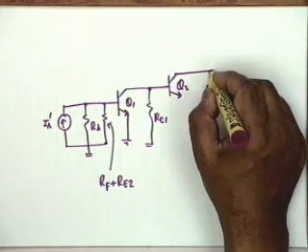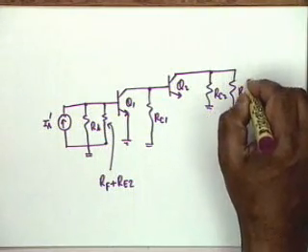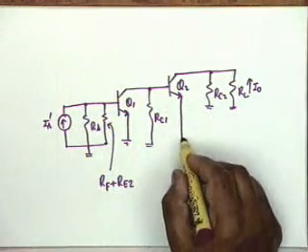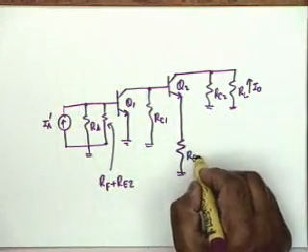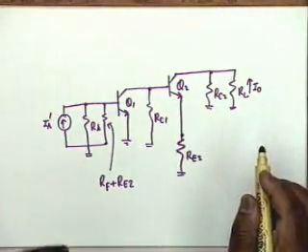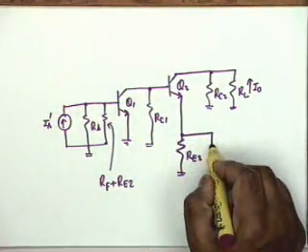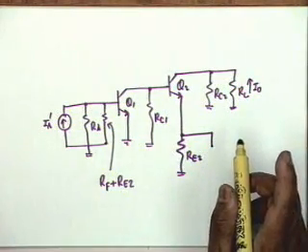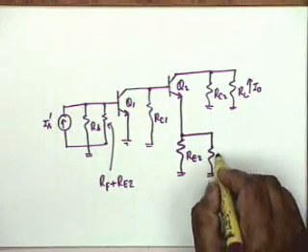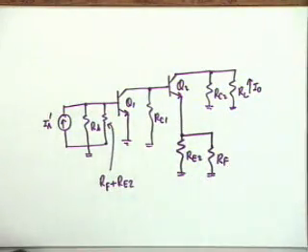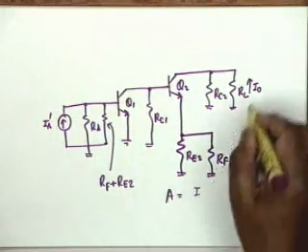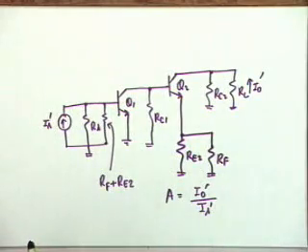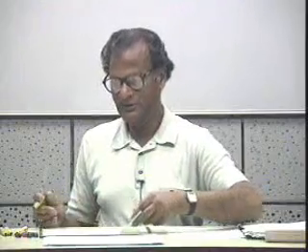Is the point clear? Okay. So you keep RL and make this I0. Then at the emitter, RE2 shall be paralleled by what? Simply RF, because port 1 of the feedback network has to be shorted. So it is simply RF. This is my A network, and A is identified as I0 prime divided by Is prime. Find out the A network, then find out the beta network.